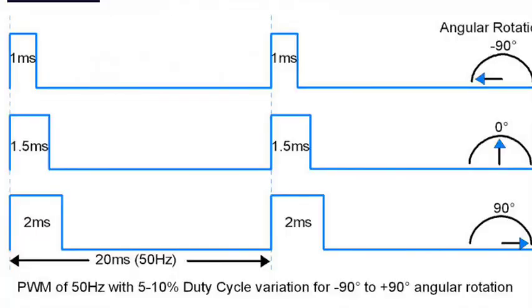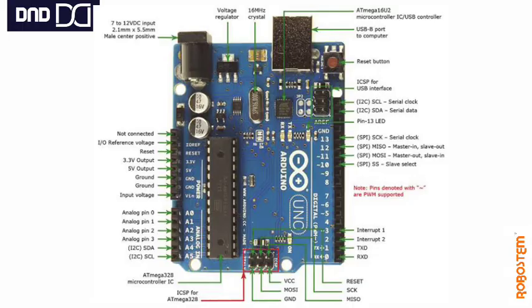If you want to see in detail what the pulse width is: at 0 degrees, the pulse width will be 1 millisecond. Then for 90 degrees, it is 1.5 milliseconds, and if you take it to 180 degrees, it will be 2 milliseconds. So this is the pulse. Depending upon the angle it is travelling, the width of the pulse will increase to power it more to cover that rotation. If you want to see this technically, you will get more details on the web.